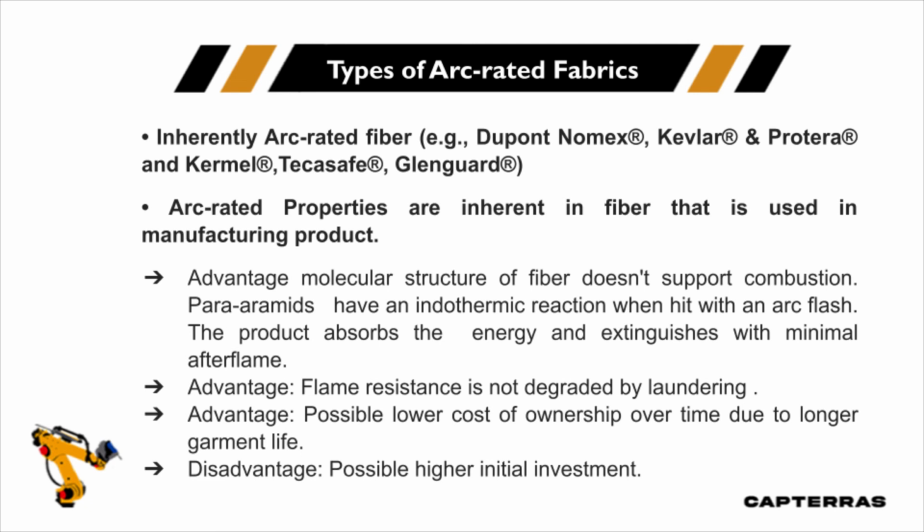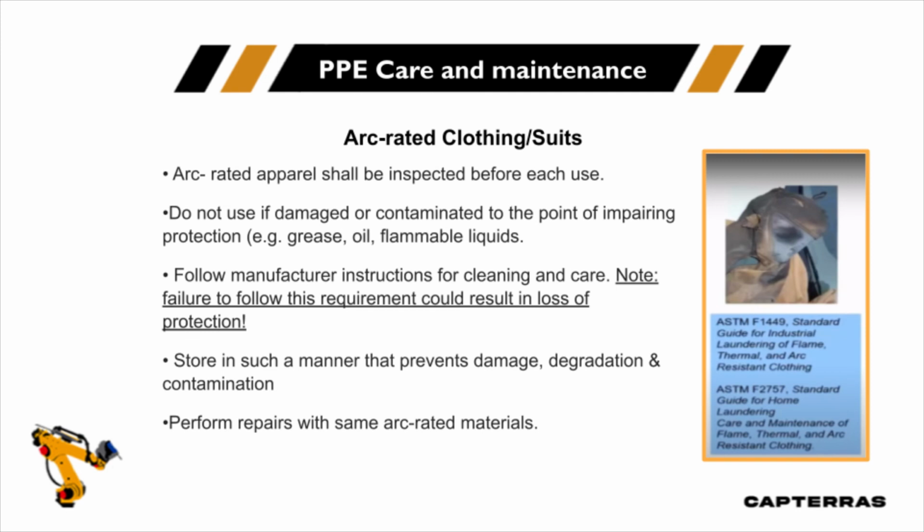There are also inherently arc-rated fabrics where we don't generally have the issue of the treatment being laundered out. The flame resistance generally isn't degraded by laundering. It does react a little differently, usually a little less after flame during an arc event, and so forth. So personal preference comes into play here, but a key thing is that, depending on what type of fabric we're using, we understand the fabric, its limitations, and so forth. Again, make sure that we inspect before we choose. Do not use if damaged or contaminated with grease, oil, or flammable liquids. Always follow manufacturer's instructions, and I've given you some recommendations over here on the ASTM standards